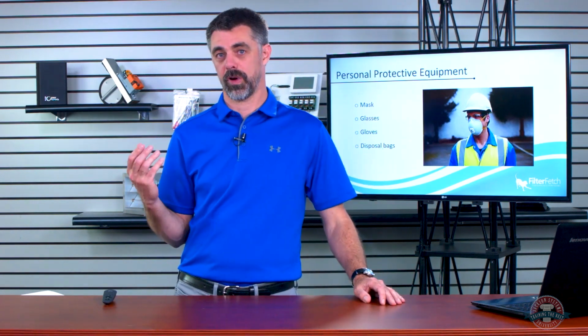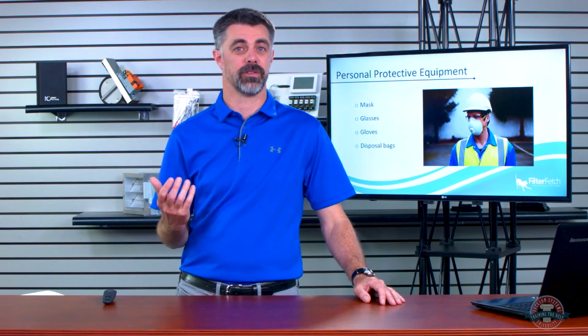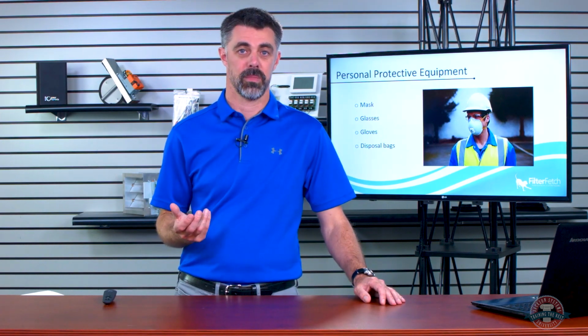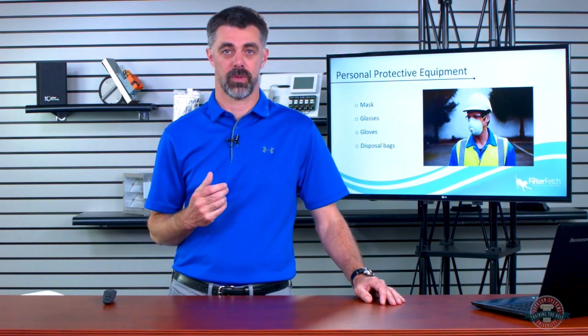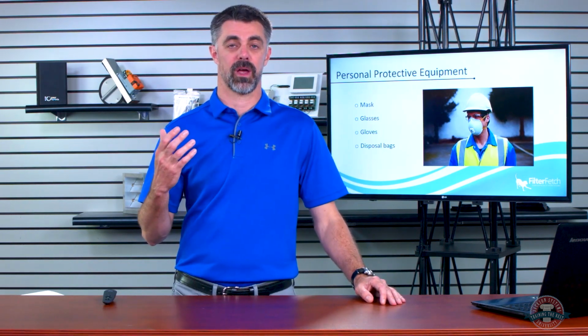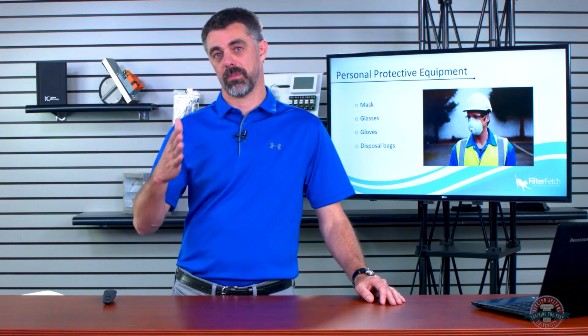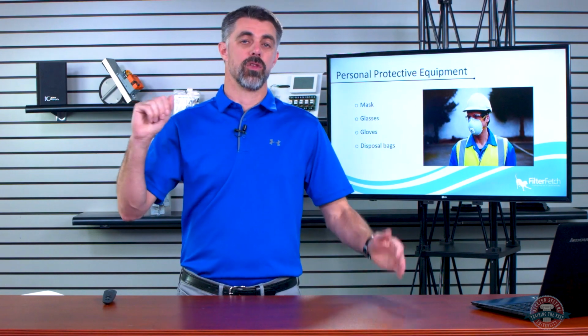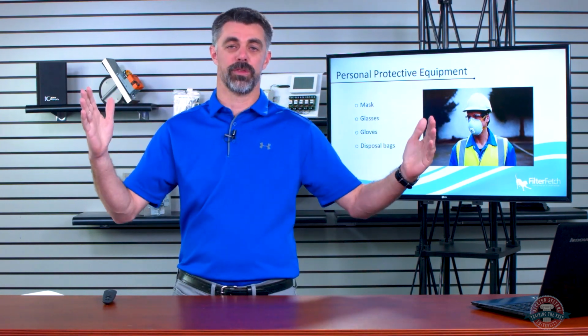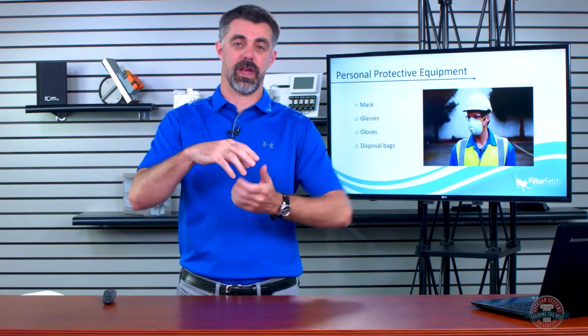Now, if you don't have sealed ducts or you have pressure differential in the house, that filter's not going to do you a whole lot of good because you're going to be bringing in those allergens from somewhere else. If, say, you have a leaky duct with filter grills on there and somebody takes out the Merv 6 or Merv 8 filter and throws a Merv 13 or Merv 15 filter in there, the allergen filters, you're going to change your pressure in that whole duct and you're going to suck in even more stuff into that duct, which means it's going to blow it out into the house.